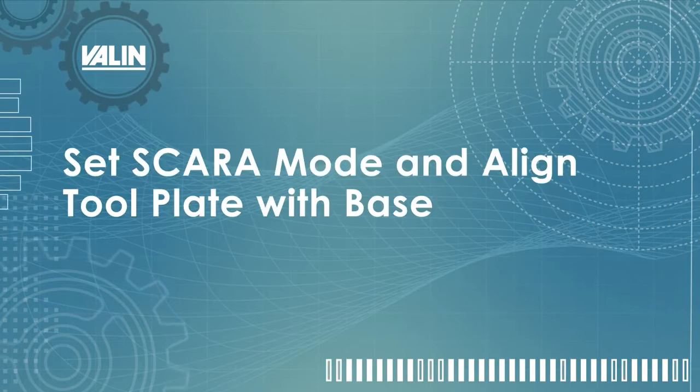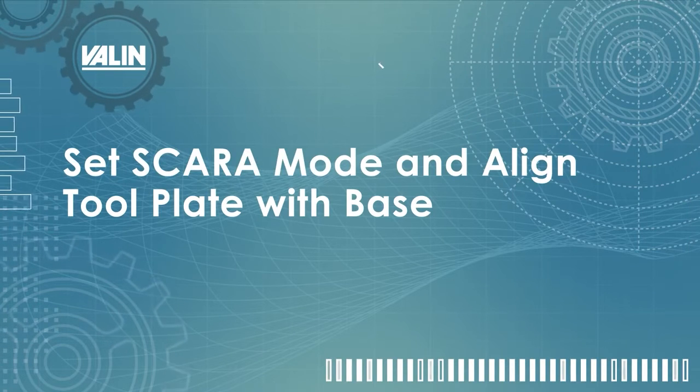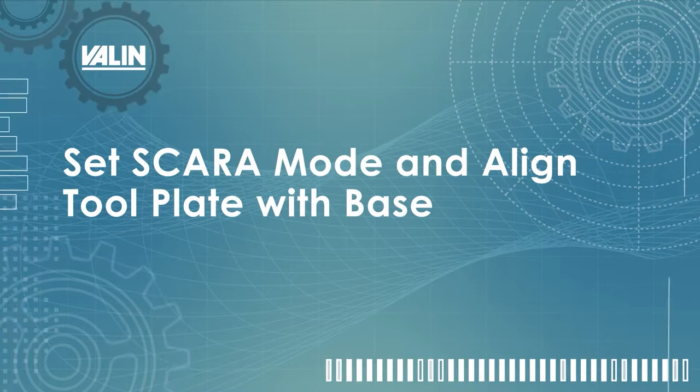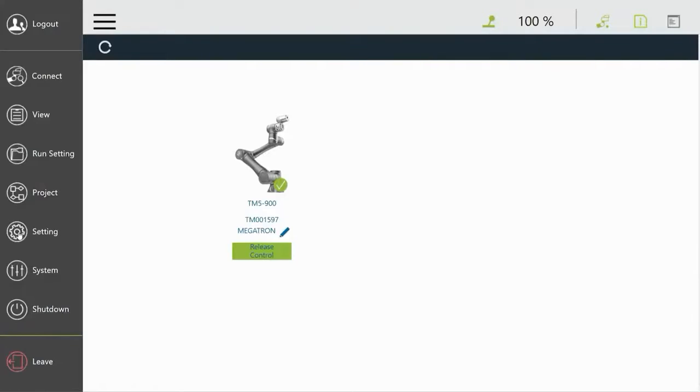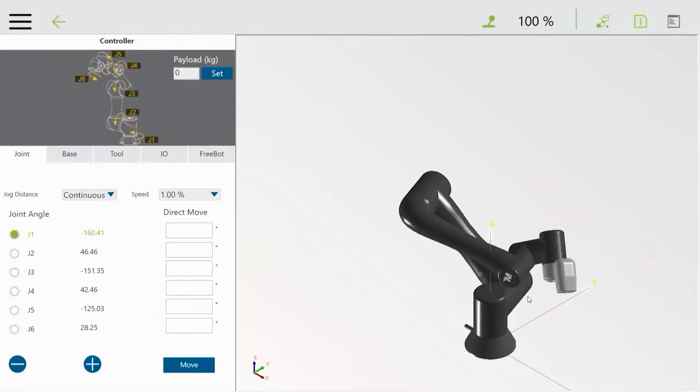Next thing we're going to look at is putting the robot into SCARA mode. This limits the joint movement somewhat so that it moves kind of like a SCARA robot. We're also going to align the tool plate with the base. Once you've got the software started, you can go to the setting menu and then go to the controller. We've done this before in a previous exercise, and I like doing this because I can see the robot here.